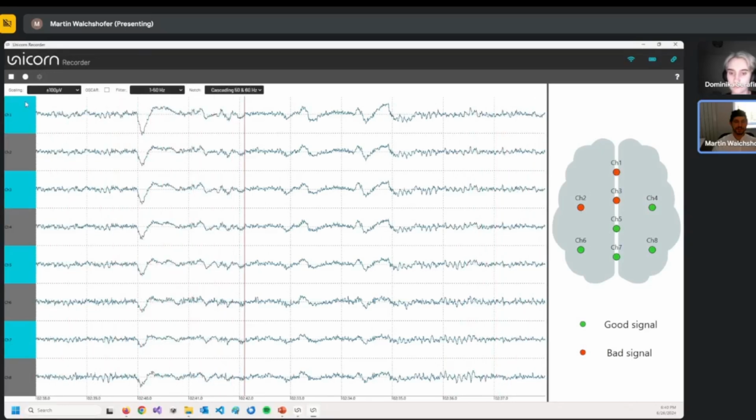And you can already see that there are some higher amplitude but lower frequency swings, and these are really alpha waves. So that's actually a real EEG signal. And all the other signals that I've showed previously are actually artifacts, and you usually don't want to have that in your signal when you're trying to do a BCI experiment.